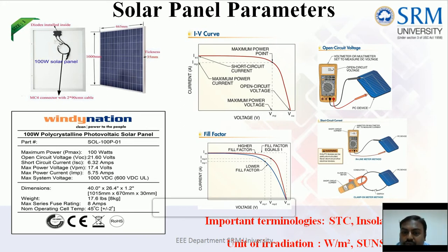That is the point where you can get the maximum possible power from a typical PV curve or IV curve, of course. That is what is called the maximum power point. So the fill factor is another index of the efficiency.